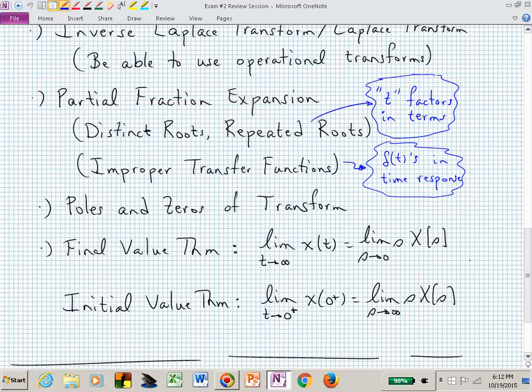But all you needed to know was really how to generalize this idea of an impedance. The impedance of an inductor is sL. The impedance of a capacitor is 1 over sC. The impedance of a resistor is R. Now you can just play with those impedances just like they were R's, except now they have s's floating around in them, and you can derive relationships for those impedances.